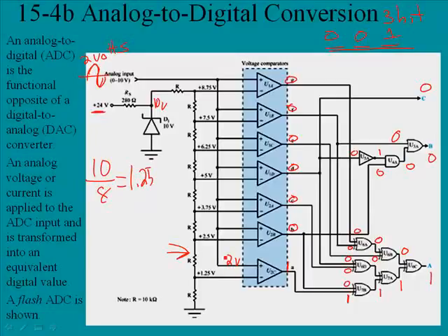Now let's do another one. Take note here, remember this is a 3-bit converter, and so with 3 bits there are 8 possible states, and that's including 0. Note that there are 1, 2, 3, 4, 5, 6, 7 op amps, so every possible value must have an op amp representation in this type of circuit.